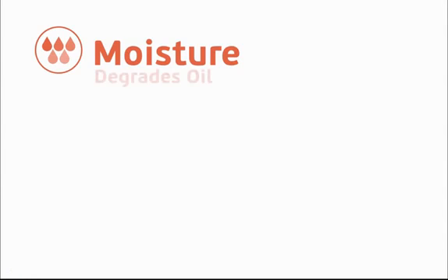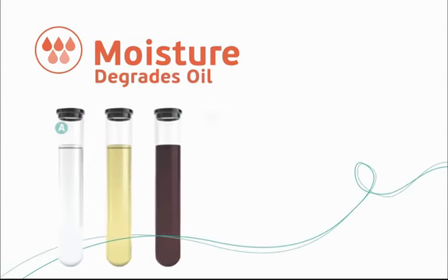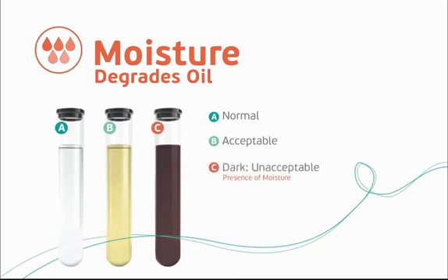Here we see 3 oil samples, with one containing fresh, unused refrigeration oil. The middle sample is the typical color after coming out of a system and perfectly acceptable. The third dark sample indicates the presence of moisture, and a cleanup procedure is in order involving an oil change, a flushing solvent for the tubing and coils, and a deep vacuum.